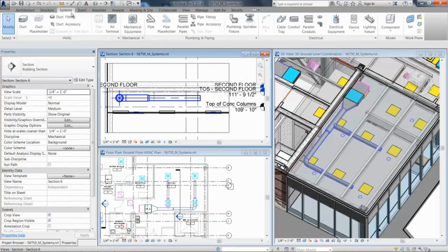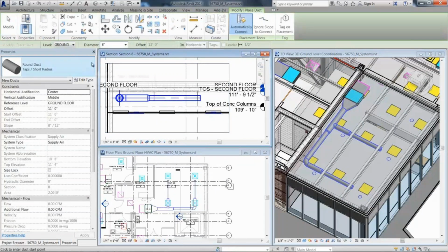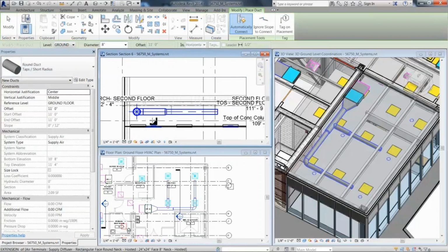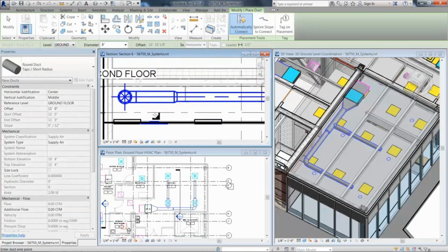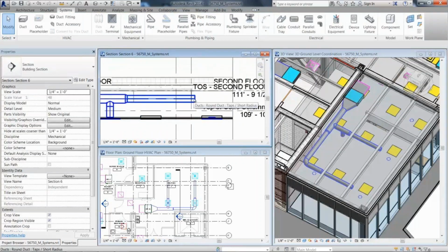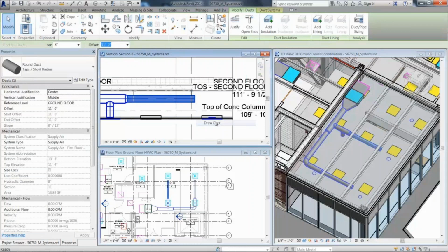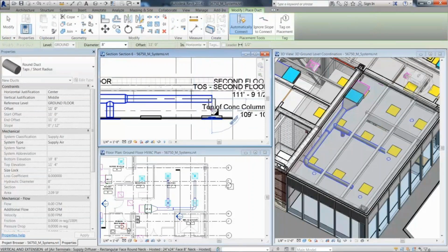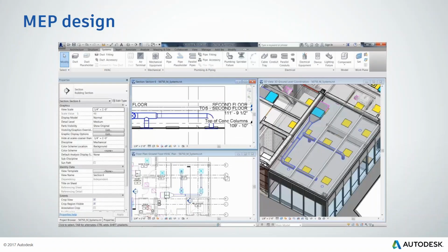So having the 3D model, layout and section, you can see that I can add, for example, in this section view, another duct, and you see that the system knows how to connect these with, for example, a T, or if an elbow is needed. Obviously, in the background there is a library of different elements, and depending on the diameter, the system is adding appropriate sizes, for example, of the T or of the elbow.